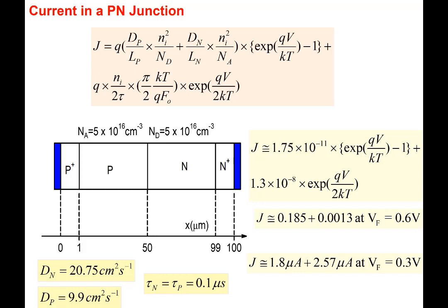The diode has to carry amperes of current, so it's a pretty large diode, with a pretty large area. If you take a diode designed for 1 ampere or 5 amperes and operate it at 1 milliampere, at very low current, it starts to go into this particular mode. If you measure, you will find you're not getting a 1kT here. This one you can call 1kT, and this one is 2kT. In many silicon diodes, if you measure, you don't get 1kT. In fact, many times you get a combination of the two.